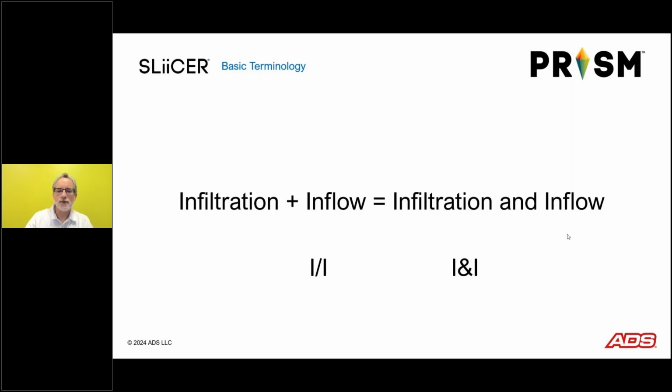And of course, the impacts of these can be significant. We think inflow is primarily that component that really eats away at capacity, especially during wet weather, and contributes to wet weather overflows. But we also think of infiltration in terms of something that's consuming capacity basically every day in our system.